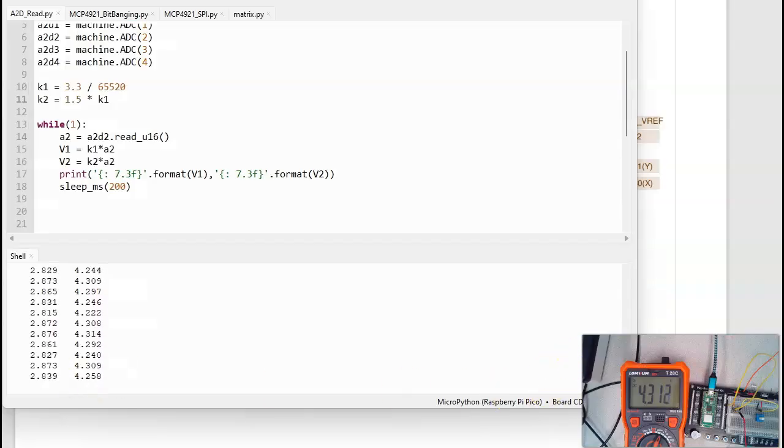okay, to illustrate that, I've got my little Pi Pico board over here, and here's a potentiometer. As I change the voltage, I go from 0 to 5 volts. That's going into my voltage divider that goes to my analog input. Here I'm reading analog input 2, because 0 and 1 are the joystick. Here's the third analog input, displaying the raw voltage, and then the voltage going through the divider. And the divider should be 2/3, converting 5 to 3.3. Inverting it, the voltage on this side is 3/2 of the voltage on the left. So when I do that, here is the voltage that I'm reading, 2.3, and here's the actual voltage, 4.3 volts.